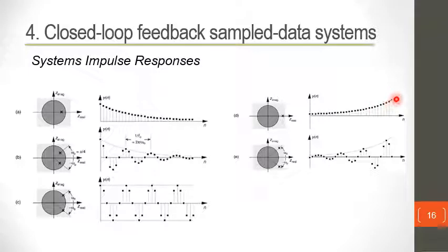It will just go up and up until it reaches unbounded, big values of infinity. This happens because the system is unstable. This one happens because the system is stable. It's within the unit circle. And then what's also interesting is that if you have two conjugate poles, and these two conjugate poles are on the right side, then you will tend to have this oscillating response here. If they're on the left, this doesn't happen.